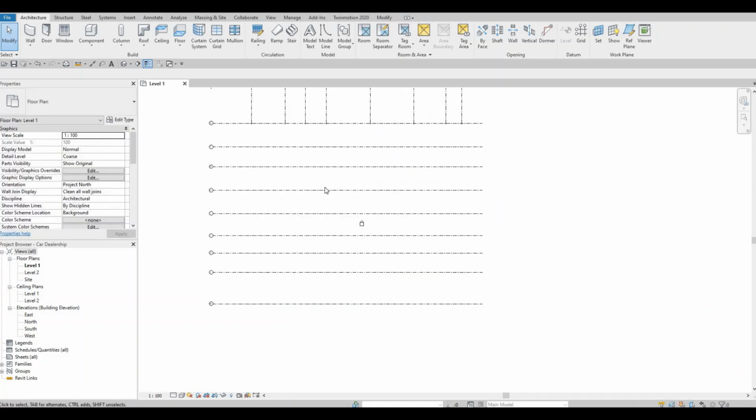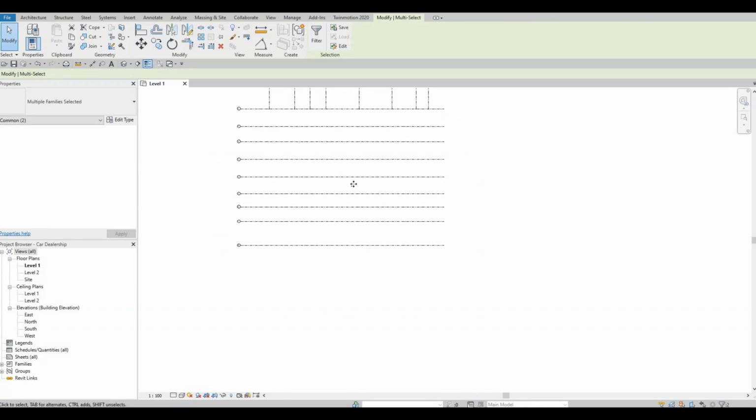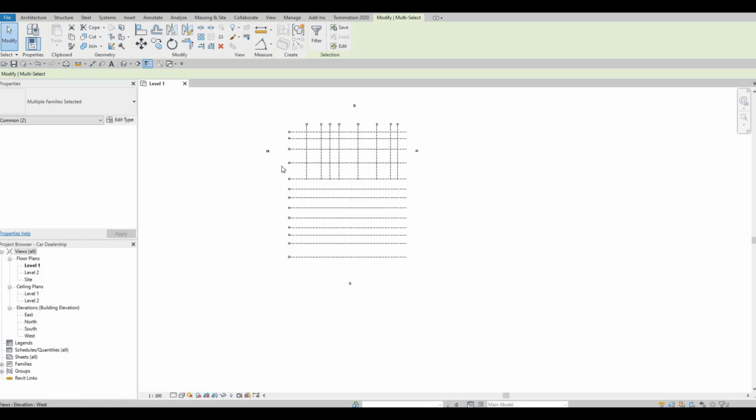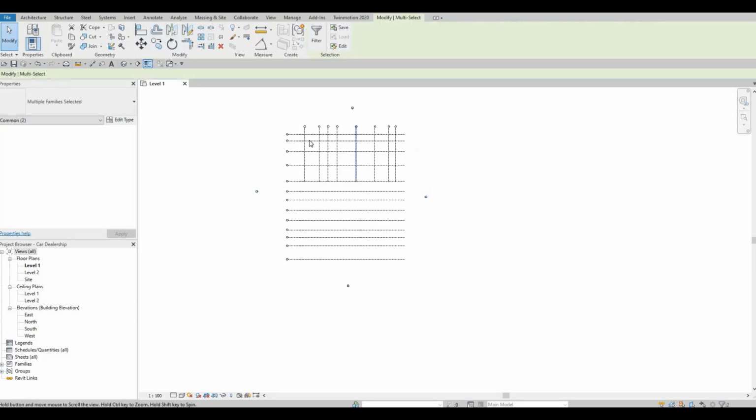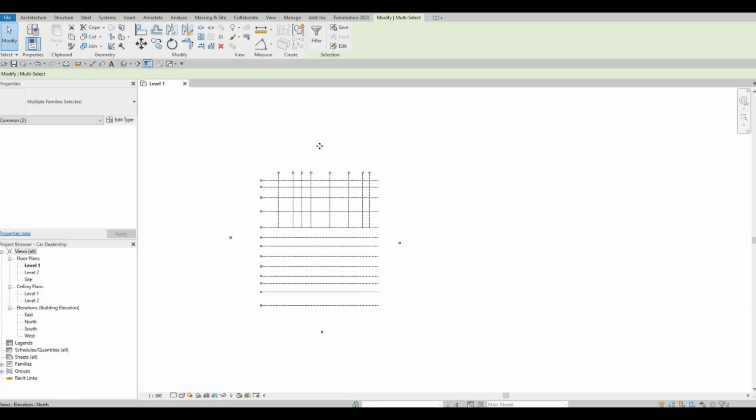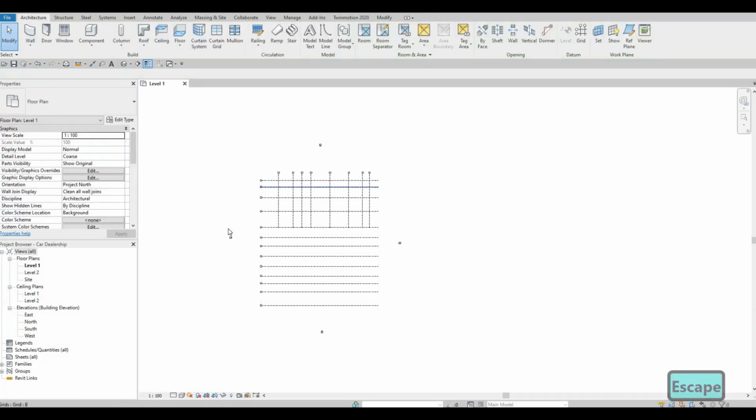And then now, as you can see, we need to move this south elevation, so I'm just gonna grab that and then move it right about here. And then here we could just center this out. This is around the center of the model, so I'm just grabbing it and then trying to center it so that the view will still see everything that is in front of it. Because if you leave the elevation tags right about here, if we create something right here, it won't see anything that's behind it.